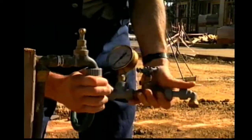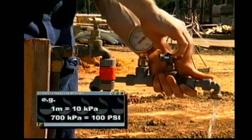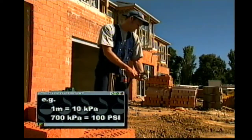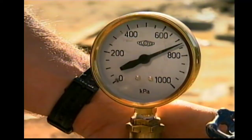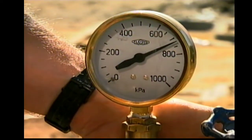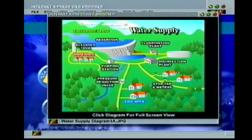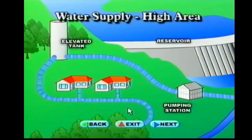When it comes to pressure, it all starts here. Pressure is basically the difference between the elevation of the property and that of the storage tank or reservoir. It's not the size of the pipe that determines this. You should always measure the pressure. Once you establish whether you're installing in a low-lying area that has a high pressure water supply or in a high area that has lower pressure, you can calculate the real needs.